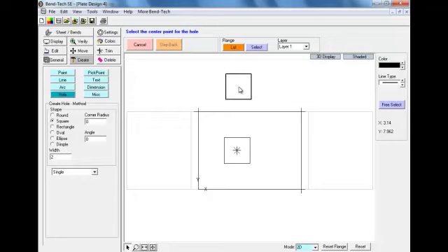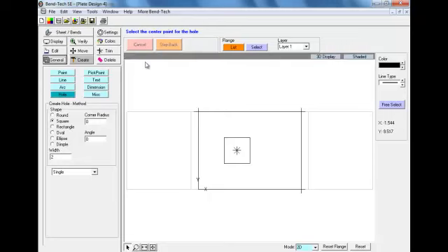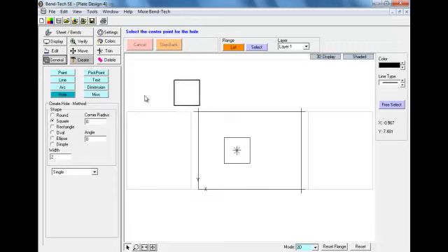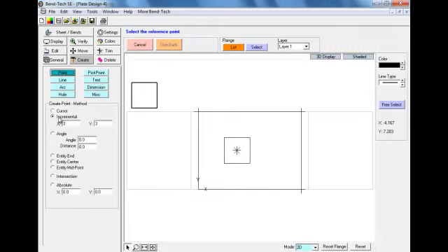For this, we need to select a couple points for that cutout. Since we created a hole in the center of our square, we can use that to create our points for our cutout. Moving to point once again, our first point is going to be 2 inches from the center point of our square. Hitting that in our incremental fields, we can place that on our last point. Our next point is going to be 1 inch below this point we just created. We will select our new point based on our last point.